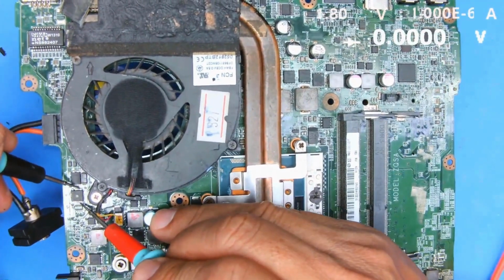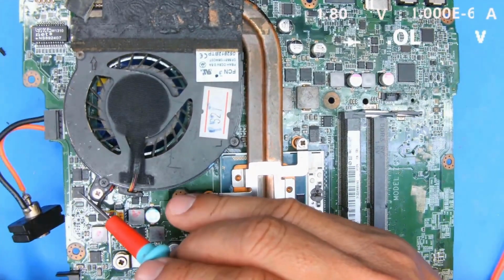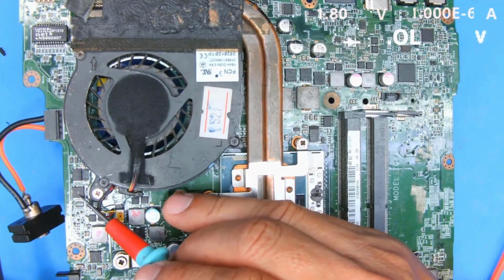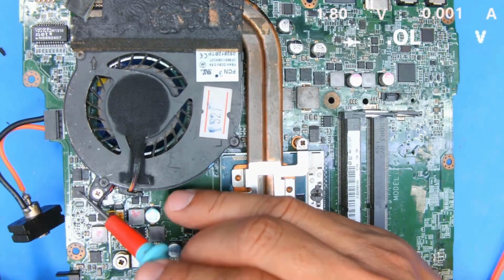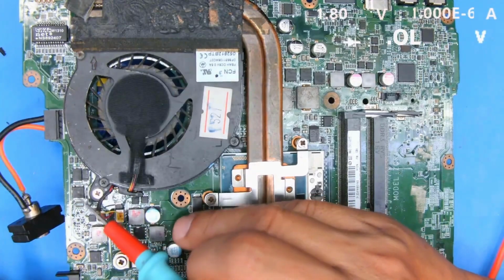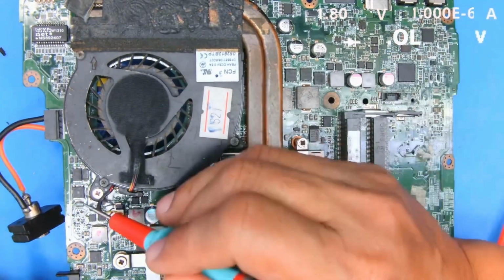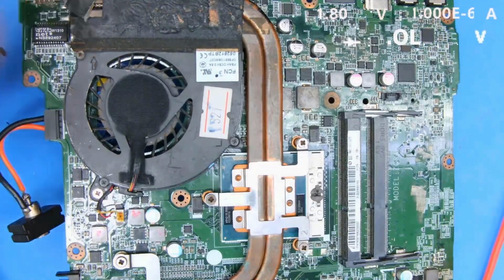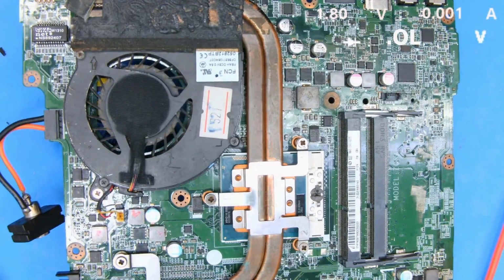As you can see here, this MOSFET is shorted, which means our power rail is shorted. But this device can still be used. It works normally and supplies power as usual. However, it will not charge the battery easily, because when this part is shorted, it will not charge the battery. So, after we have finished repairing the high voltage section, we need to check here and replace the component properly. Only then will it charge the battery.